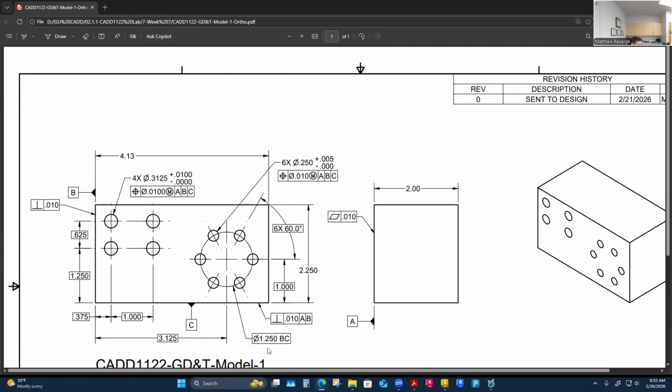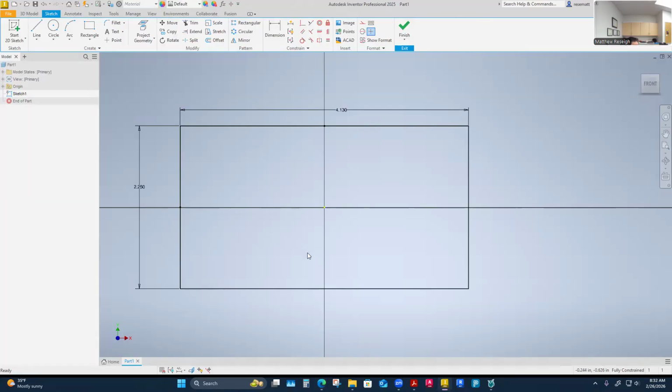And there's a piping chapter we'll study in our theory book over the next eight weeks, so they'll talk about concepts of piping systems a little bit. Long story short, the bolt circle is 1.25 inch. These holes are 1/4 inch, so I'm just going to draw them at that size, 1/4 inch, on a 1.25 inch circle. Yeah, let's put that in. I'll put this hole in first and I'll just pattern it around. And I think I'll just do it in my sketch on this one.